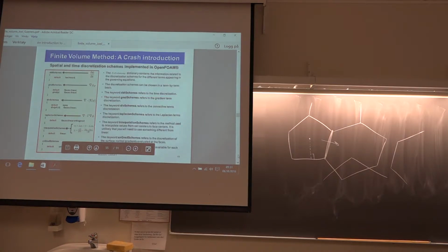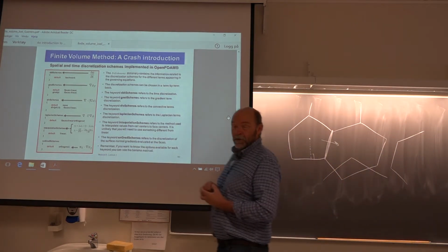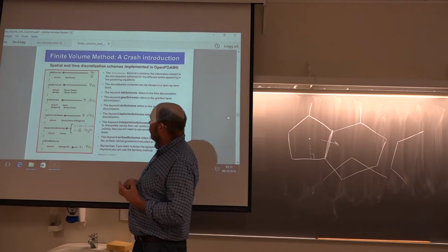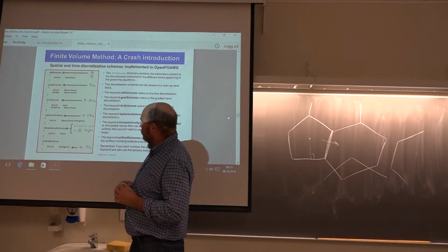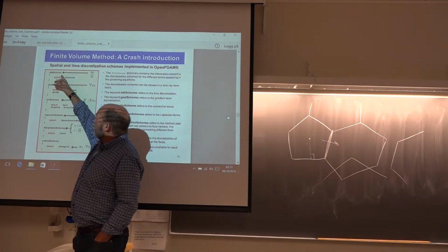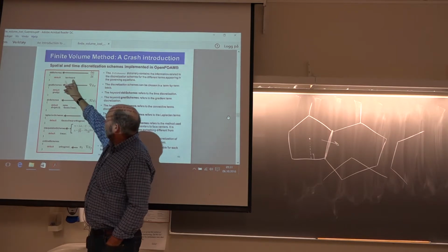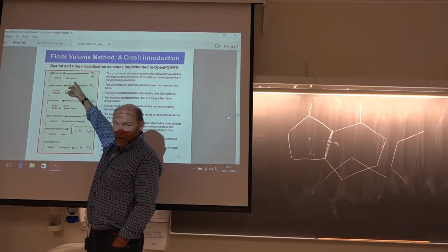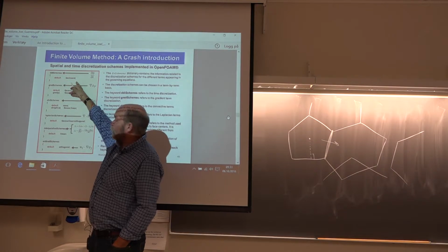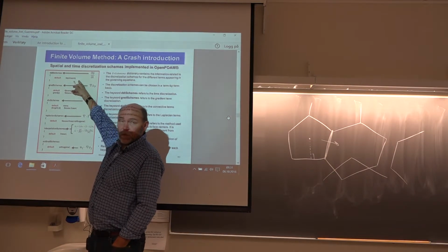And now discretization schemes. Here you have the layout, the stencil for the fvSchemes file, as I showed you earlier. So time derivative. Here the default is set to be backward. That would be the first order backward Euler step, fully implicit.